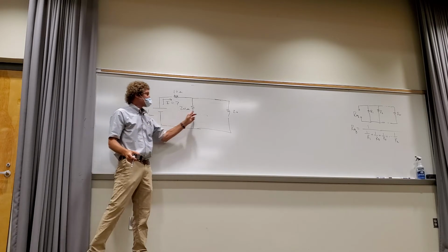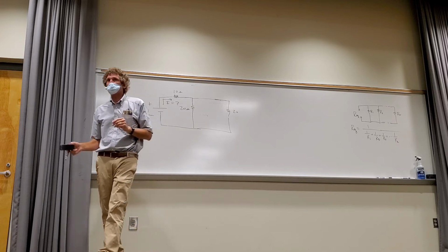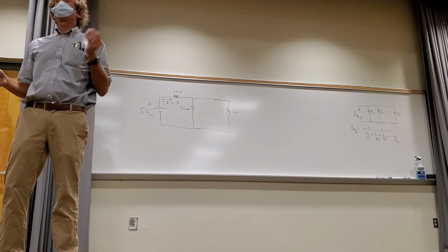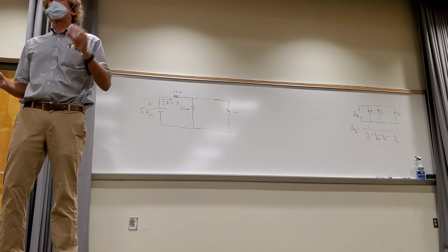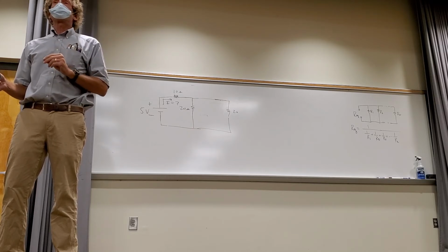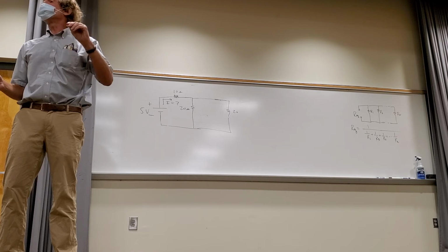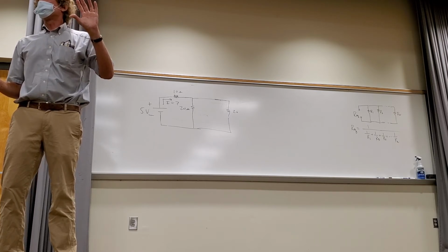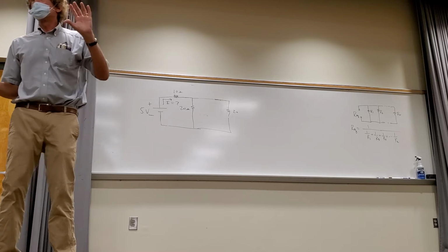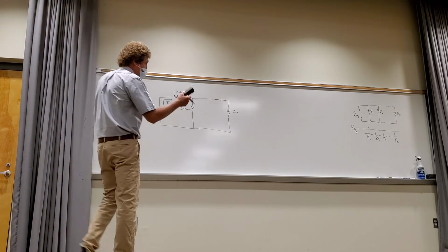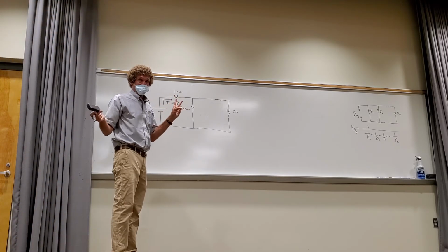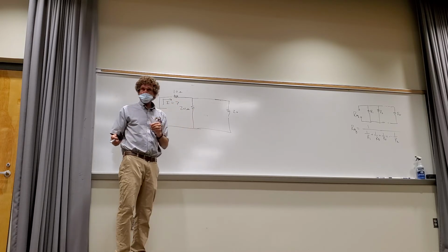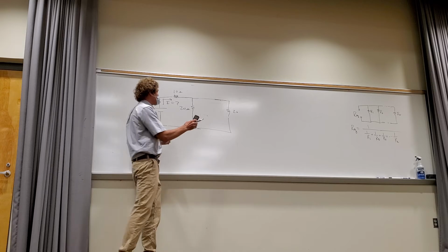Here's a trick. Identical resistors, if you have 2 of them, you take the value of 1, divide by 2. 3 of them, take the value of 1, divide by 3. N of them, take the value of 1 and divide by n. You all hear me on that? It's a nice little trick. So here I've got 2 in parallel. You can do the math on it, it works. All right? And I can see that this could be replaced by 10. Do you agree with that?